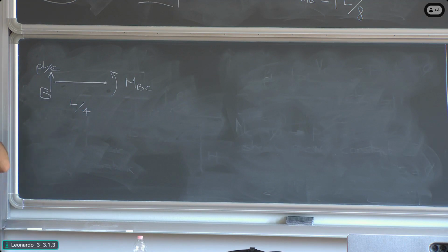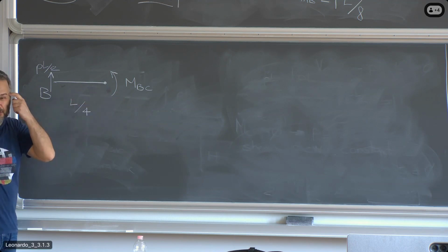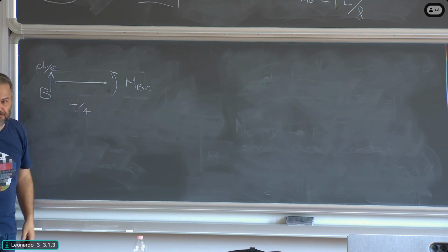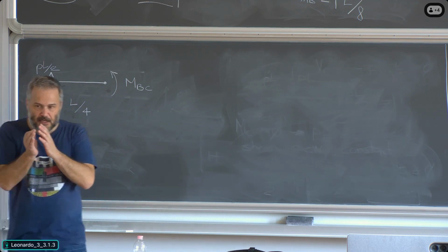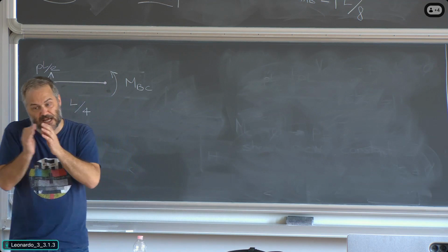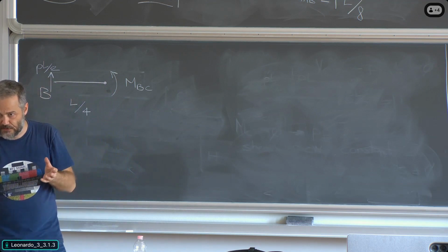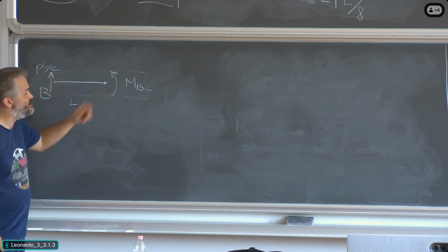Careful about one thing. In this case, I cannot say that the shear force here is 0. It's not 0. There is a discontinuity. It doesn't make the shear force equal to 0. It means if you move slightly to the left from midspan, it has a value, and slightly to the right, it's another value. They are different in sign, equal in value. But the shear force here is not 0.